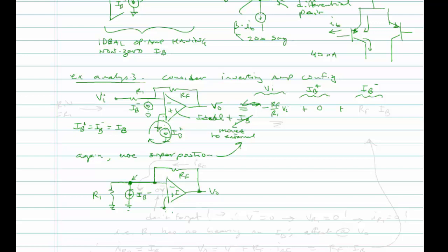I wonder if they're in parallel, and so I do a current division deal. Or maybe I'll do the parallel of them, and then take that parallel resistance and multiply it by the current and get the voltage at that node. But wait a minute, this is actually no ordinary passive network. This is an op-amp. And there's negative feedback, and the node we're talking about is the inverting input.